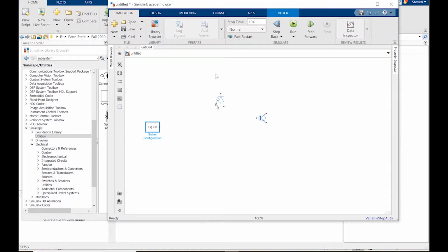So in Simulink, the various blocks, it'll solve one block and then move on to the next, and then move on to the next. So it has a unidirectionality to it. Whereas in the Simscape models, there's no arrow on these, that's a signal, and that does have directionality, but it's more of a passing energy. So this is much more realistic of a physical system than a mathematical representation, which is more what Simulink is. And so this solver allows Matlab to solve the system of equations simultaneously. That would be the most amount of detail.